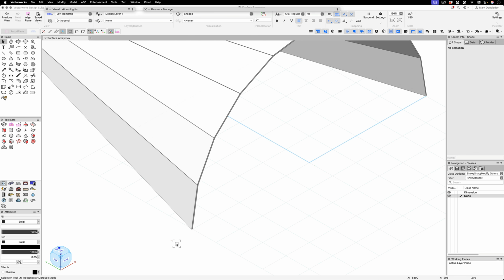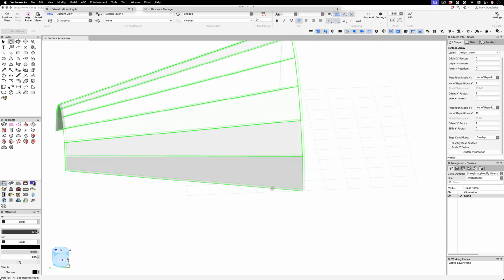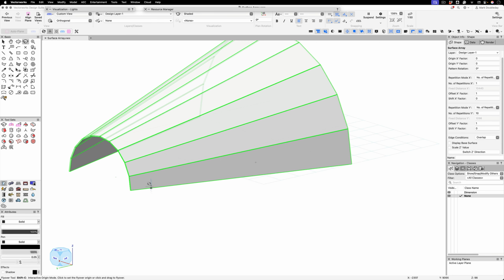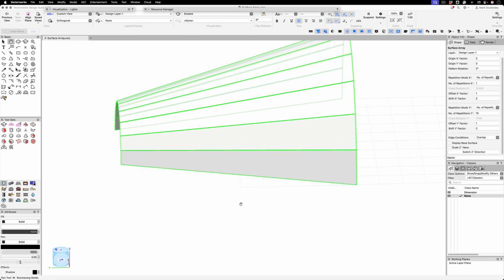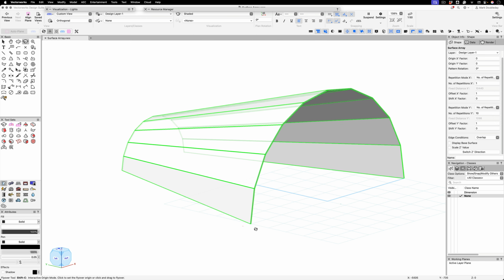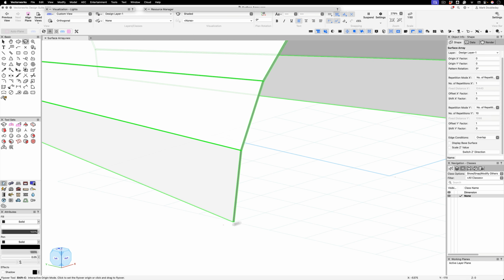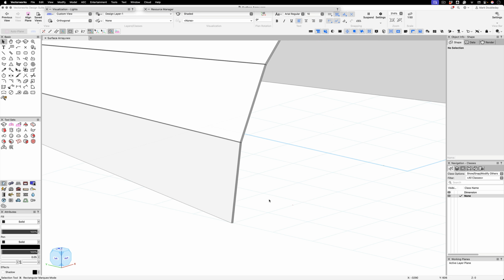Essentially, extruded objects such as extruded rectangles will rescale, so you've got a much fatter edge there. Then if you go round the end here, you can see that it is indeed tapered down to a much slimmer edge here, and they will rescale according to the shape of the surface. What they won't do is rescale in the Z direction, so you have to change that yourself.